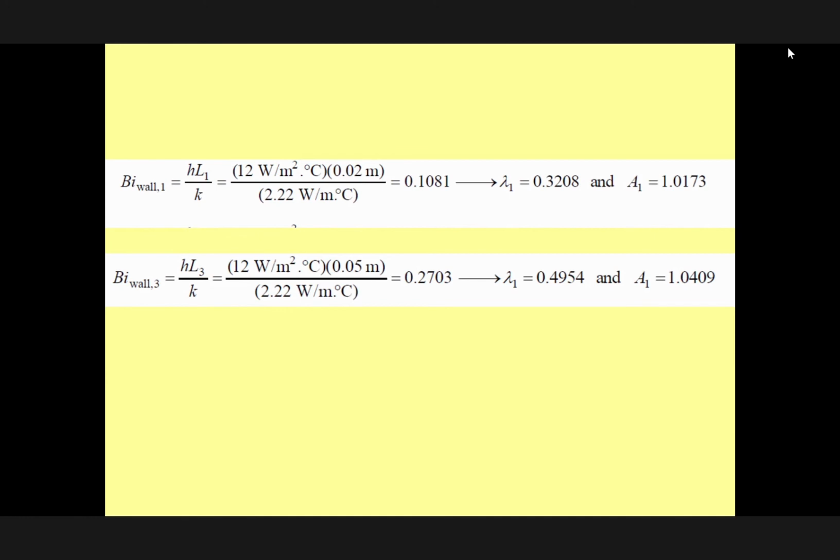The solution I have here, I have for a wall of 10 centimeter. Okay, that's why it's my 2L, 10 centimeter, my L becomes 5 centimeter. Therefore, that's why here we divided by 2, here we kept that, because we assume here is symmetric, okay? And we find this value is again more than 0.1. Therefore, I cannot use a simplified equation, okay? I cannot use the simplified equation.